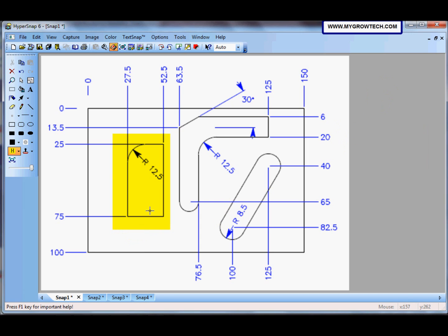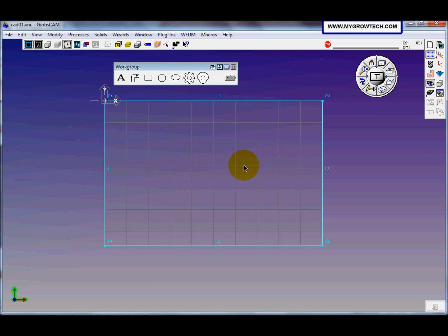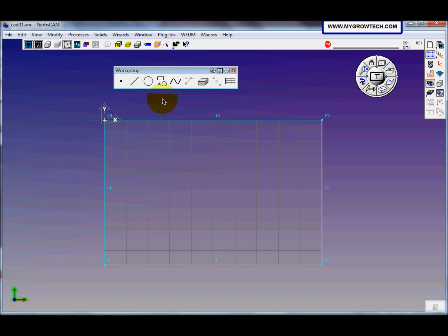Now step 4, I'm going to create this feature shown by the yellow region. Let's go to Gibbs. Okay, so let's return to the previous here. Just click here, and now I'm not going to use a shape to create my next features. So I will use the line. Here you have line by two points, a point with angles. I'm going to use this one, axis.